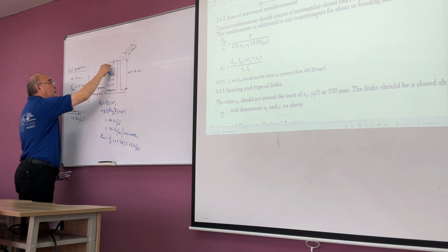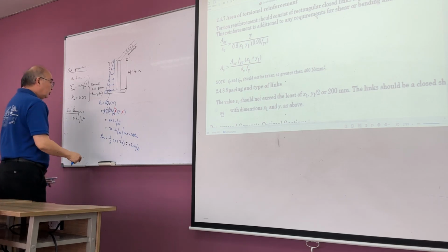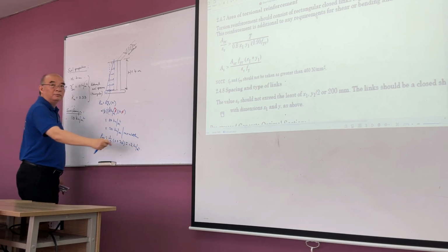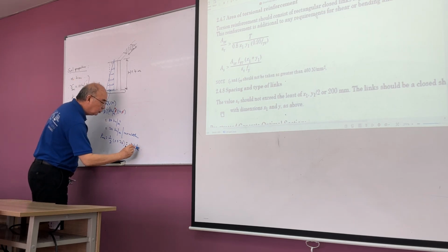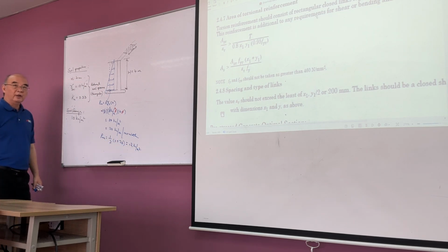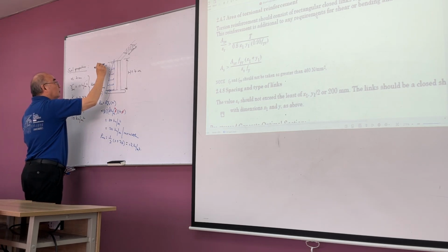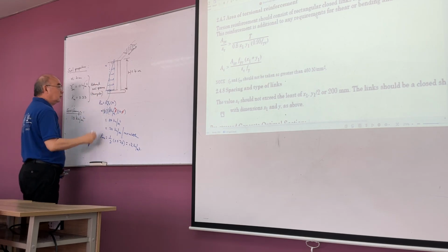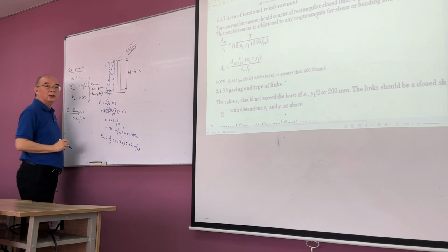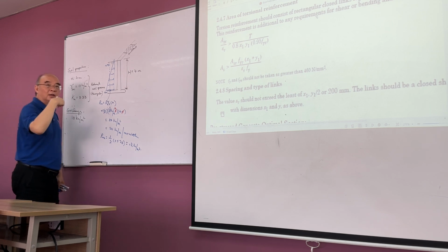So if you cut this one and put it here, it becomes the average. Understand? So this average stress is 12 kilonewton per meter square, which is per meter width, right? So this is 24, and the average is 12 kilonewton per meter width, right? Okay, understand?